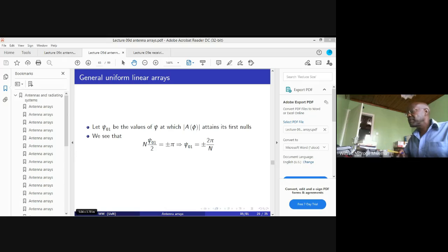If you are dealing with sinusoidal or time harmonic time dependent fields, you don't have to put the time in there all the time. You can always work without it, because most of the Maxwell's equations are spatial derivatives, and any time derivative can be replaced by j omega. And therefore we'll put in the time when you are asked for the instantaneous values. I hope that one answers you.